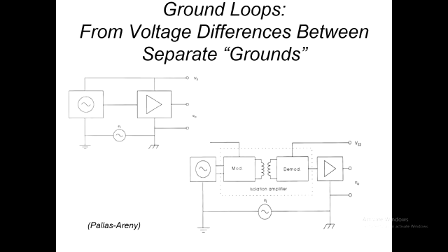Okay, so how do we do it? As I've said, we've got two separate grounds here and an isolation barrier in between, and there'll be some passage of signal across that isolation barrier. Here it's shown as being modulated on the transmission side, demodulated on the reception side.